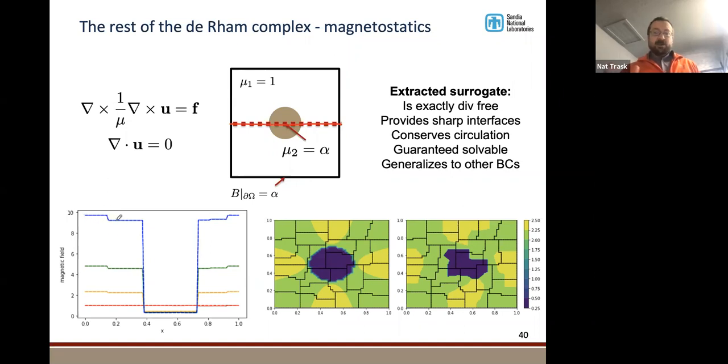This holds in the forward simulation world: if you're simulating electromagnetism with regular finite elements and you're not very careful, you'll get these kinds of ringing phenomena. There's a technical explanation of what goes into that, and there are decades of research in the finite element world on how to properly simulate Maxwell's equations. In a hand-wavy way, I'm just going to note that we're getting a sharp representation of this jump in the solution.